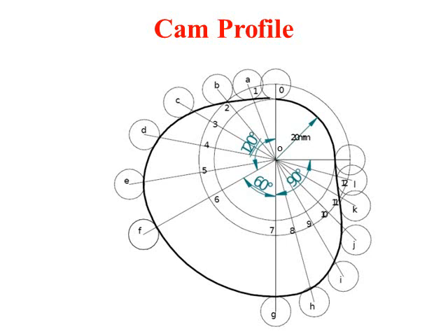Now, after marking all the points, as in the earlier problems where we have drawn the prime circle and the pitch curve, now these points A, B, C, D, E, F, G, H, I, J, K, L can be joined together by dotted lines, and that becomes the pitch curve.